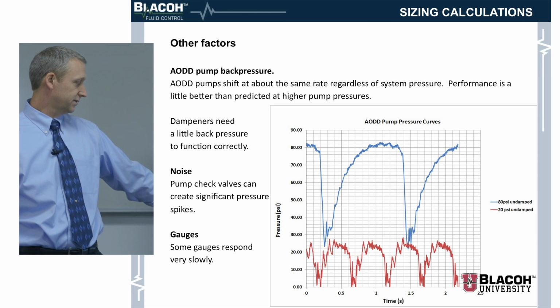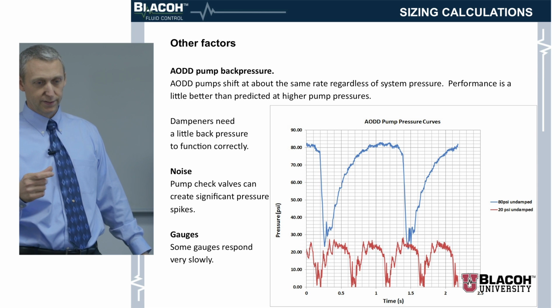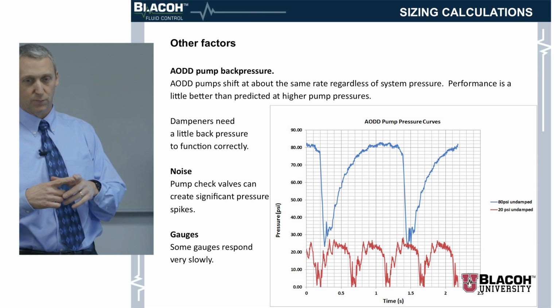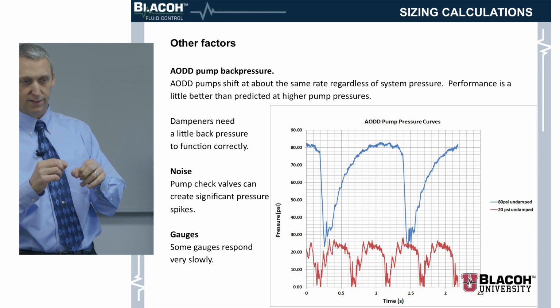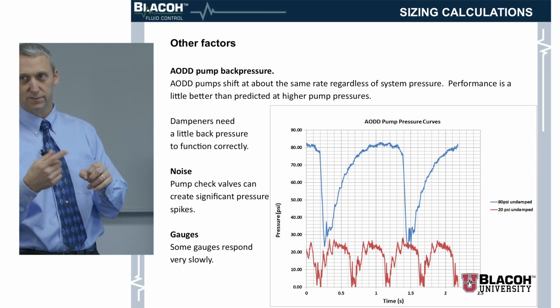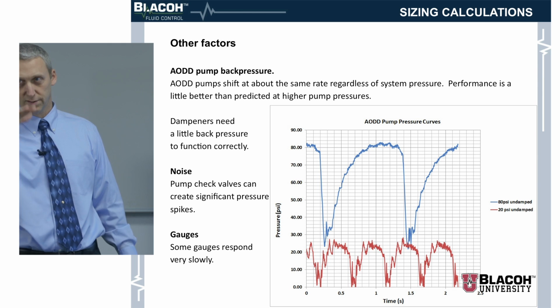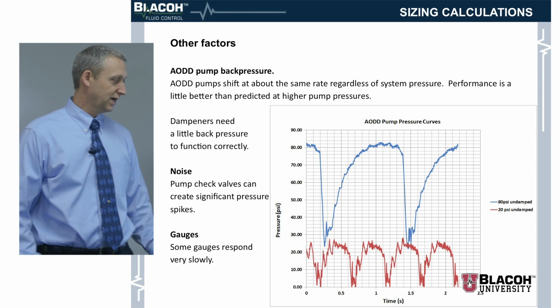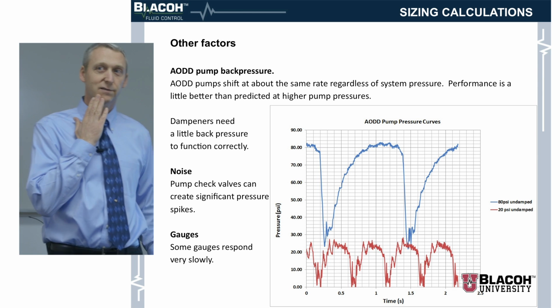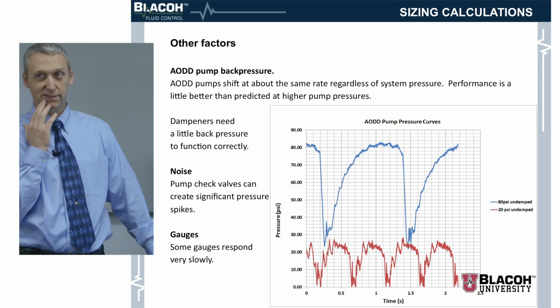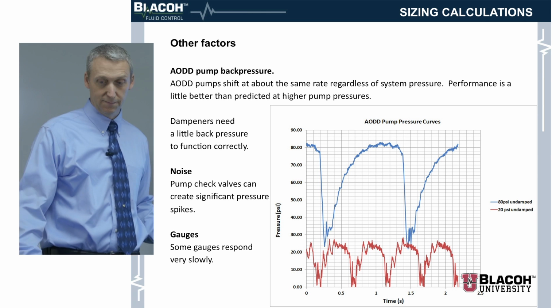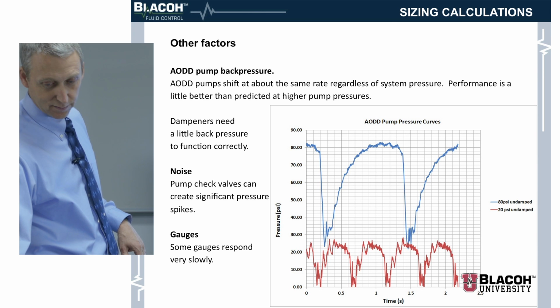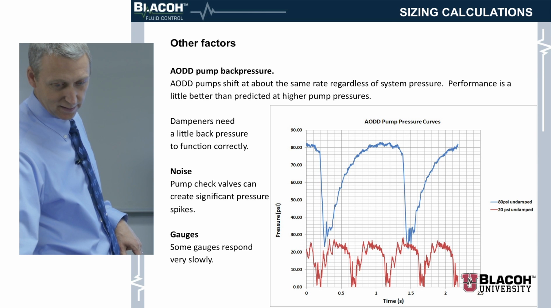Another thing to look at: sometimes you'll put on a tube gauge that has a little meter on it as a telltale, so it will tell you where the highs are. We've had some cases where they've overshot quite a bit in rapidly changing situations. That's something to consider as well. Or they will undershoot, depending on the speed of what's happening.